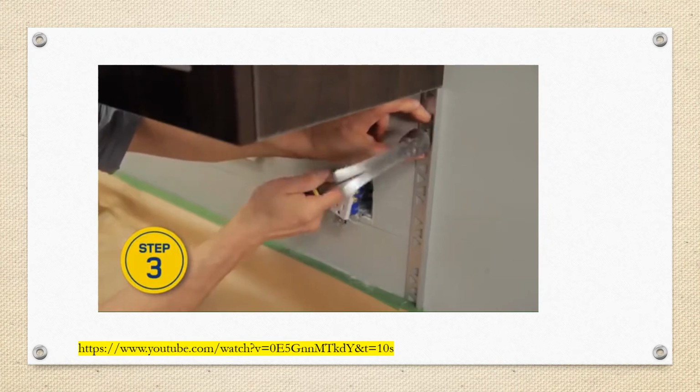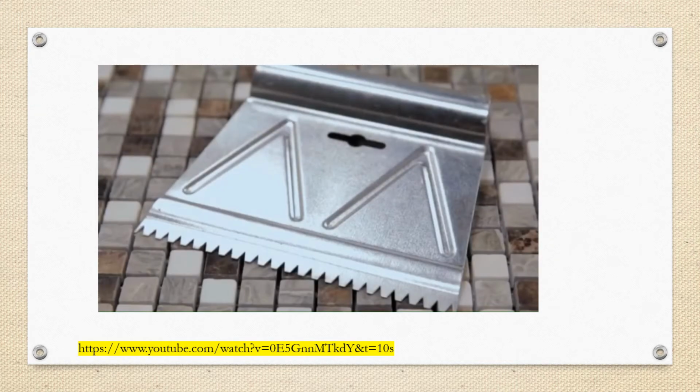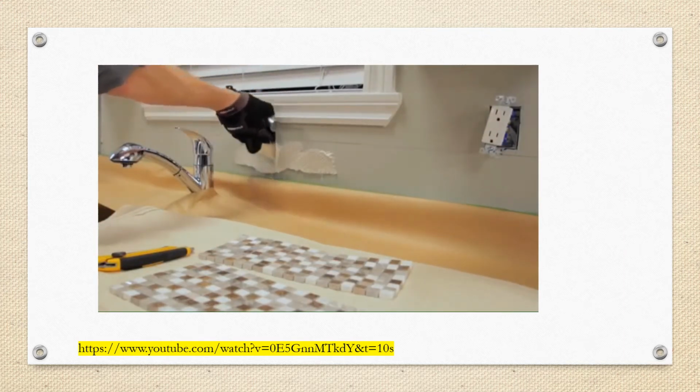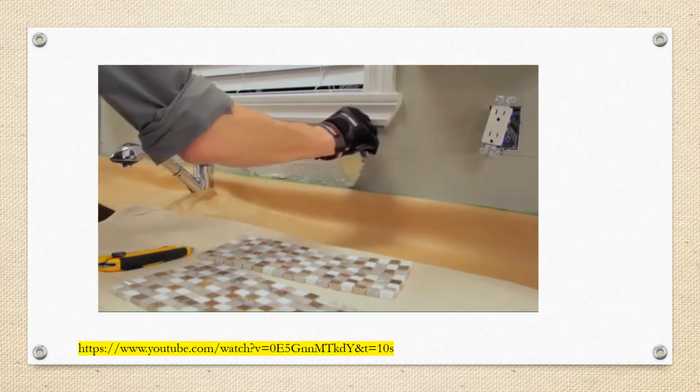Install a tile finishing trim at the edge of the tiled surface with flat head nails. Using a 3/16 of an inch notch trowel, spread a thin coat of tile adhesive over a small section of wall to one side of the vertical line. Hold the trowel at a 45-degree angle. Cover an area of 3 to 4 linear feet at a time.